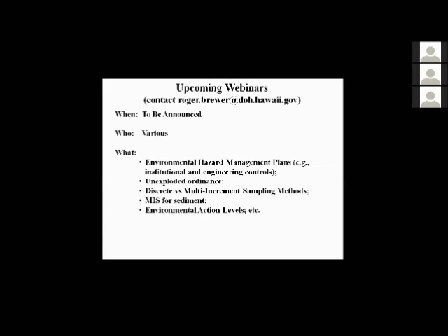Another question is on the effects of rain and moisture. Rain obviously can cause the pore spaces in the soil to be filled up, and the gases will not be able to diffuse through those pore spaces while they are saturated. However, you put the samplers out in dry or just typical conditions, and then you have a rain event and the soil pore spaces fill up with water. Gases will not be moving then, but as the water subsides after the rain event ends, gases will then start moving again. And because we're using hydrophobic adsorbents, they will continue to absorb compounds even if they become wet. It's not necessary to have a membrane or plastic around them to protect them.